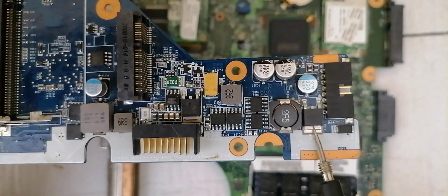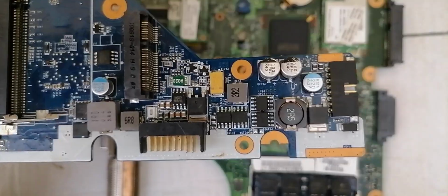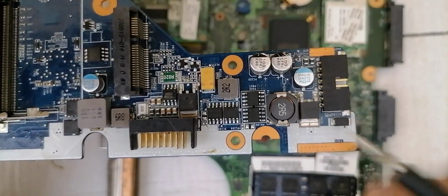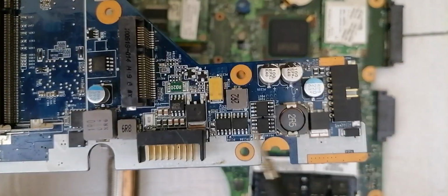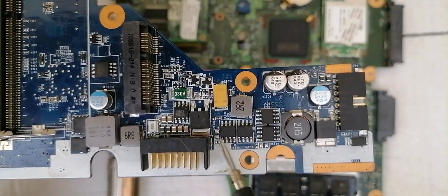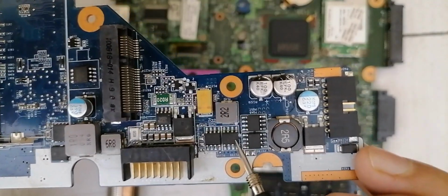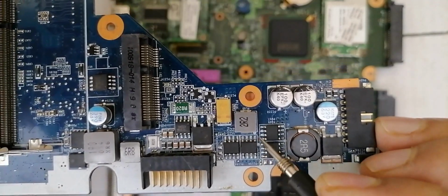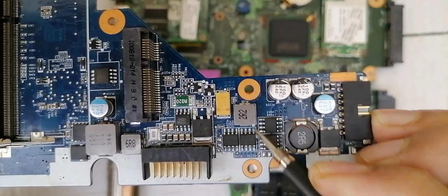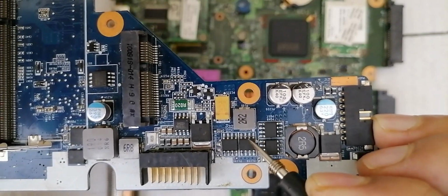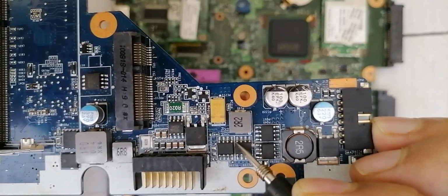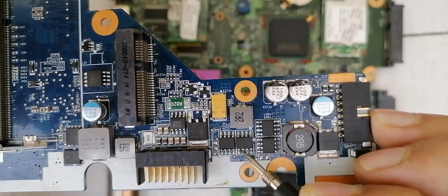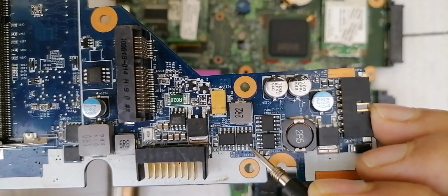Or you can even find this kind of MOSFET, as you can see, with 3 terminals. So this is a 3 terminal MOSFET. Here we have the source, drain, and gate. And we have the 8 terminal MOSFET, as you can see. For example, to identify the first pin, we have this dot here. Do you see this white dot? It means this is pin number 1, pin number 2, pin number 3. So these 3 pins are source. Pin number 4 is gate, and the 4 other pins are for drain.